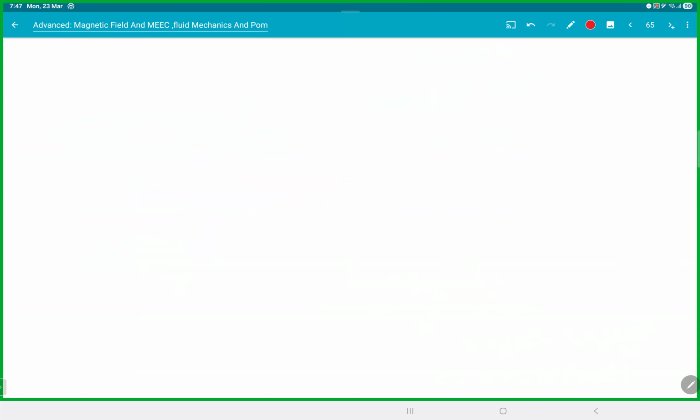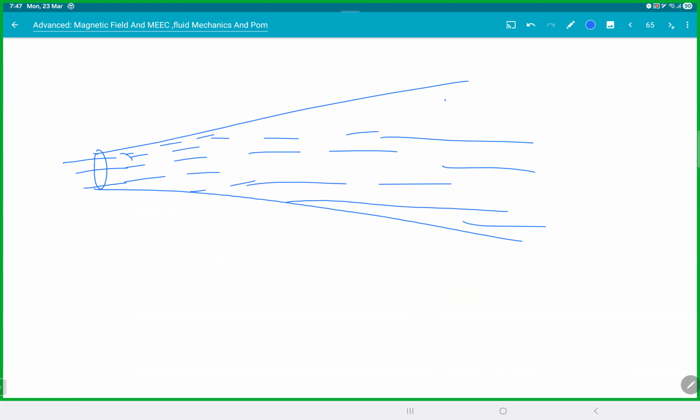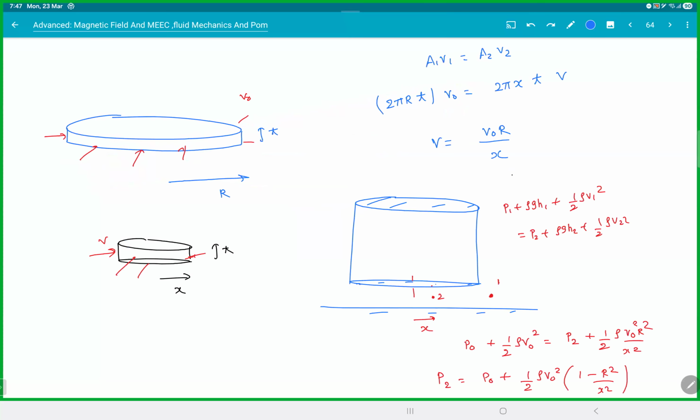See, I'll give an example. Let's say I have a pipe which is becoming bigger and bigger like this. Now, if I send liquid through this, do you think it will occupy the whole pipe? It will occupy for some time. It will slow down, slow down, slow down. At some point, the liquid will start going like this and you'll get a gap at the top, right? You're getting it. So the mistake, the reason you're getting negative sign is because you assumed it will occupy the whole space for the entire distance. Are you getting the catch?